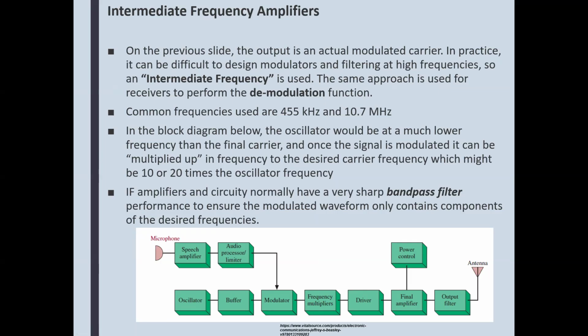Why? Because higher frequencies are closer to noise. And that's one thing. The other thing is higher frequencies have less energy. So the equipment has to be really, really well made. If it comes to a receiver, it has to discriminate really well between the noise and the intelligence, and if the noise is compared with the carrier, for example, then it is more difficult to accomplish that, the higher the frequency.